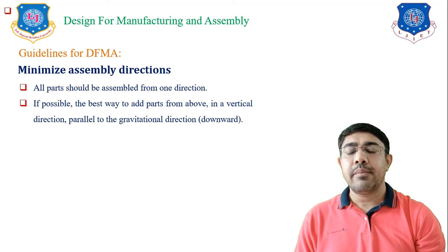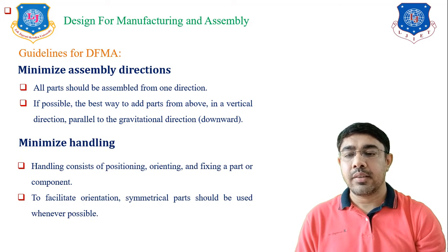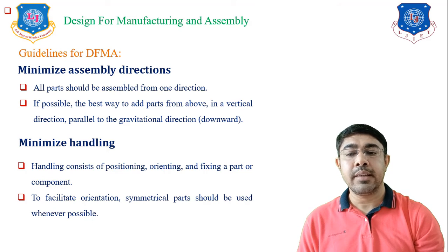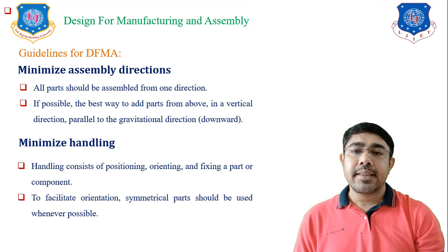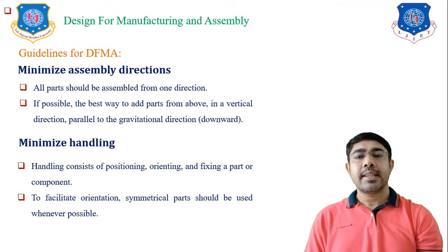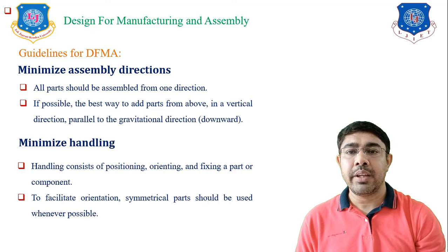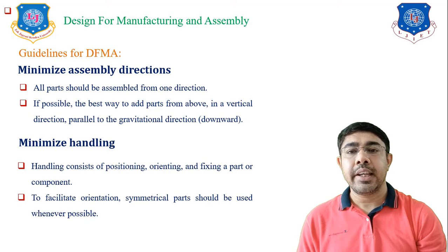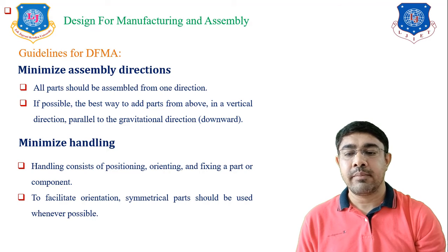Next is to minimize handling. What is handling? Handling consists of positioning, orienting, and fixing parts or components. So when we design components, we have to keep in mind that all the components can be easily handled while doing the assembly.